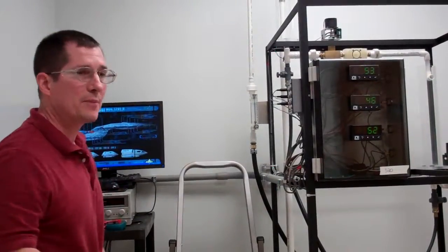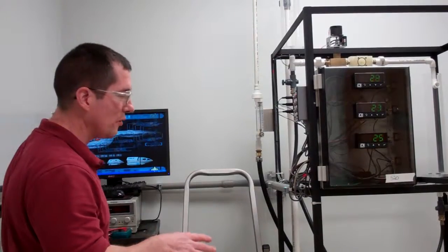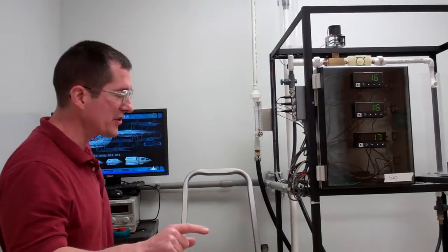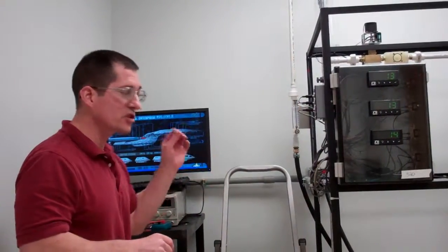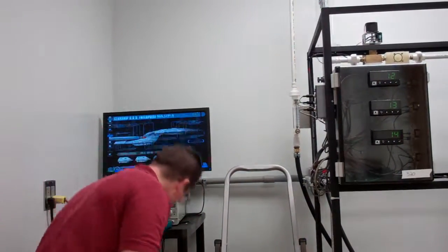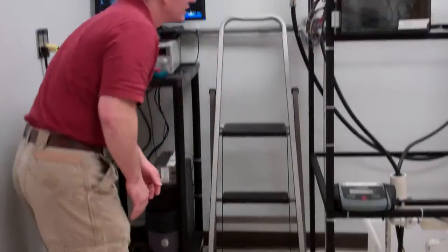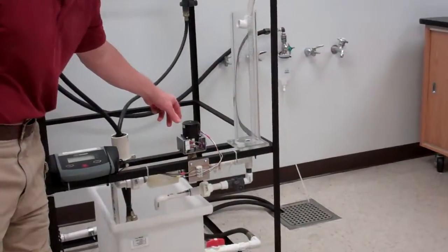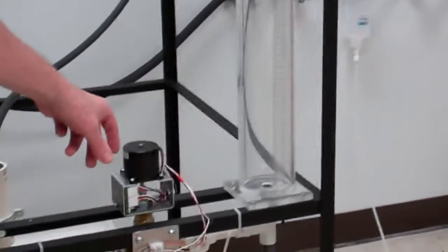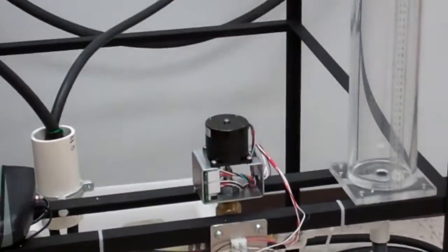So you can hear what happens when you turn on power to these control valves. What happens is that they go all the way to the closed position, and so you're going to hear them stall a little bit. That's a normal sound. So you can hear them. They're going to the completely closed position, and it'll stop. The noise will stop in just a few minutes.